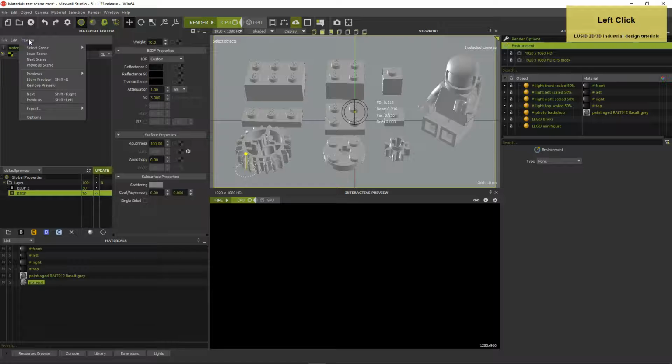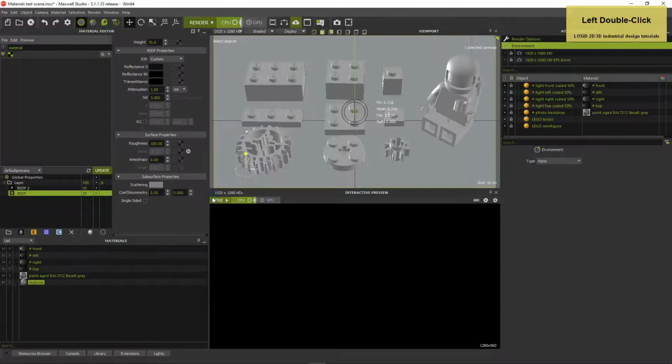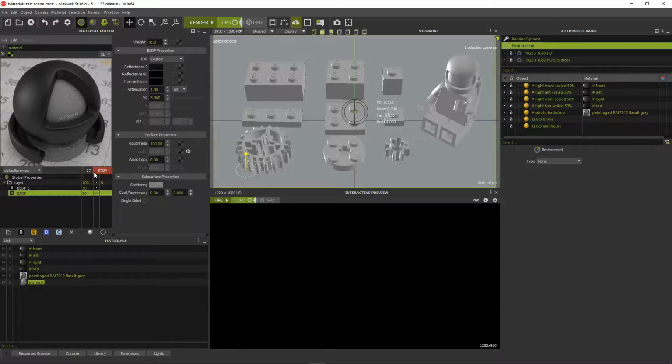In the Material Editor's Preview section, load the symbol scene and in the options set the sampling level to 20 and render time to 5 minutes. Then click Update. If you want to save a material for future use, you want an accurate preview icon so you or your colleagues know exactly what a material looks like.